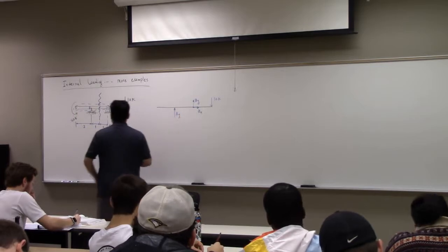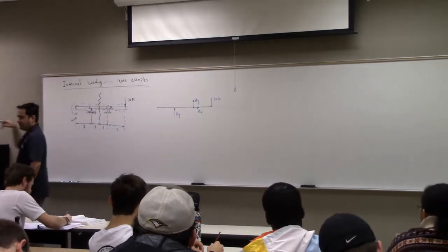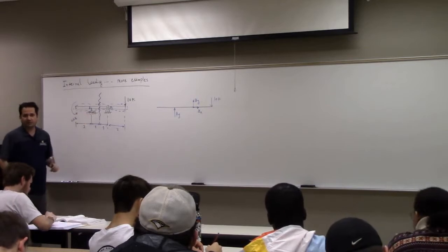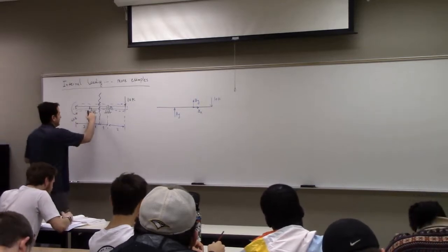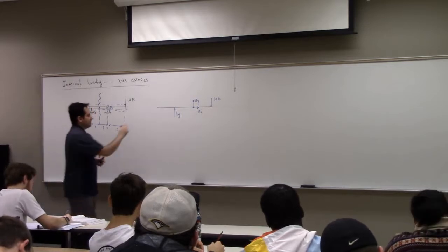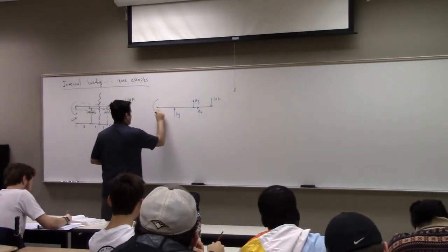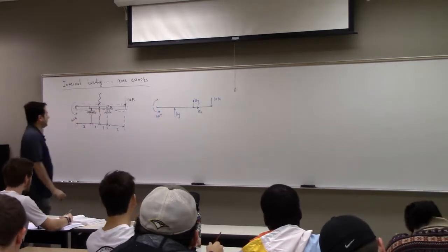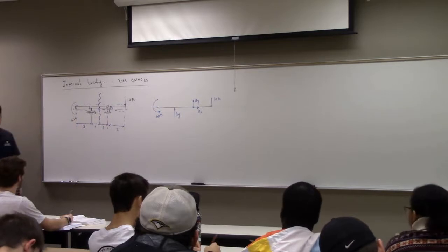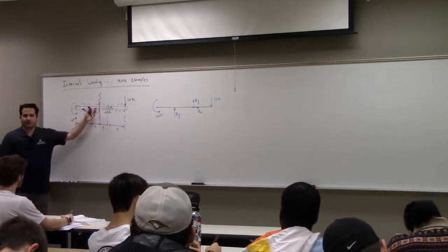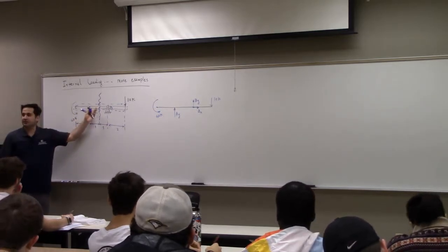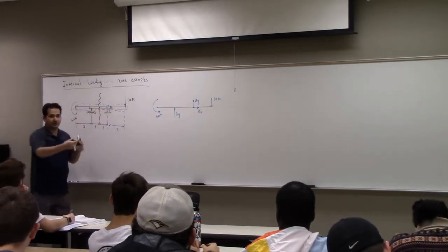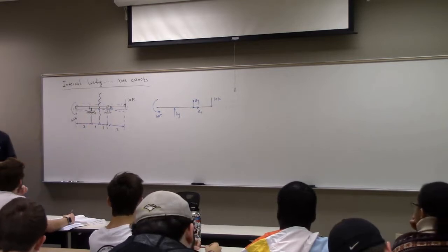Why don't I put the Ax here? Because it's simply a roller. There is nothing that can hold it up against the x perturbation or axial load. So this is the final thing, the bending moment here, 60K. And that's all you get for that. Should I include Cx, Cy, and Mx? Why? Because for this big system, it's all internal loading. They cancel out from right and left, right?